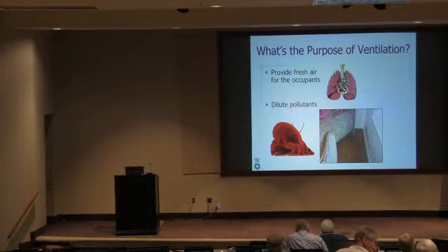If it's fixed capacity equipment, it's on or off, and it uses the same amount of energy when it's on. It's just a question of runtime. And I'd rather have that runtime for 2 hours recovering with effective dehumidification when I'm home than have that runtime in 4-minute intervals throughout a 12-hour period when I'm not there.